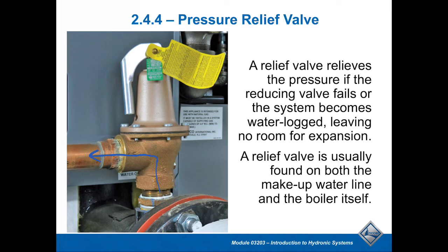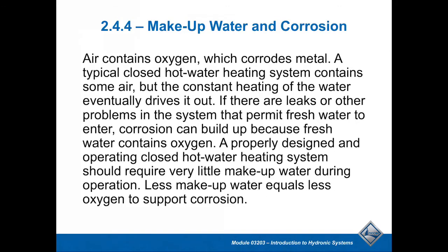This could be, or maybe you had an expansion tank that became waterlogged. You have to be very careful of that, and make sure that those are functional and working on a system. The most common pressure that those relieve at is typically about 30 psi of pressure.